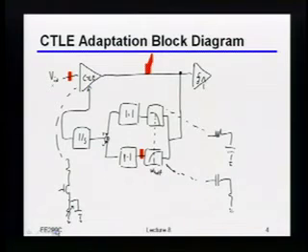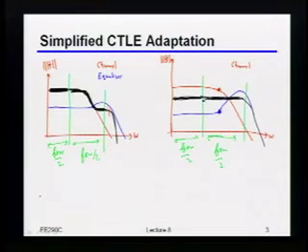Is that the reason why it's 0.48 or whatever? Is it for I data? I think that actually has to do with the fact that you don't necessarily set the equalizer bandwidth to 0.5 of the bit rate or whatever. You set it to 2/3 or somewhere in that ballpark. There's some optimization you run there. Again, I don't think it's actually super critical unless you care down to, let's say, the last few dB or whatever it is.